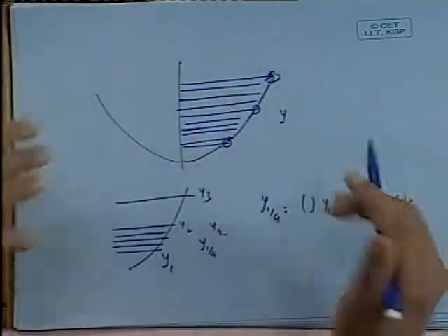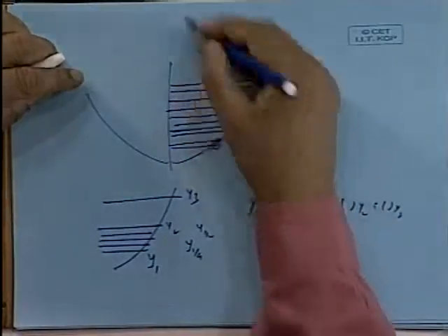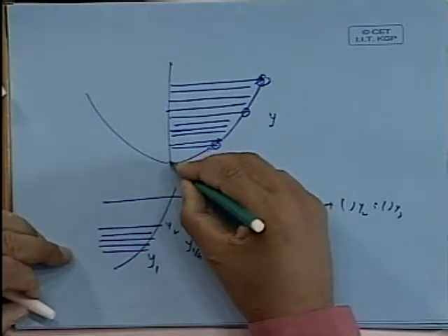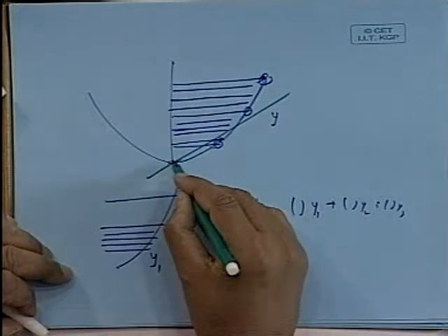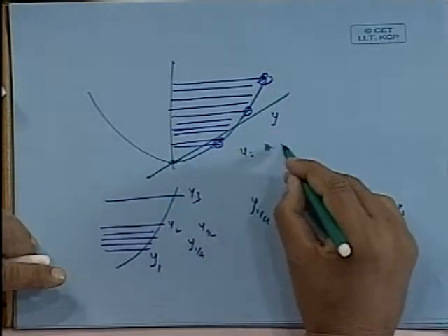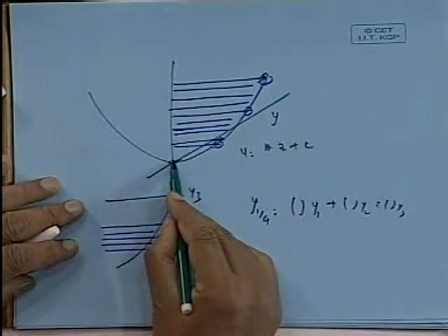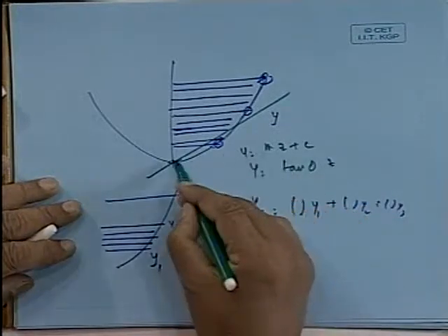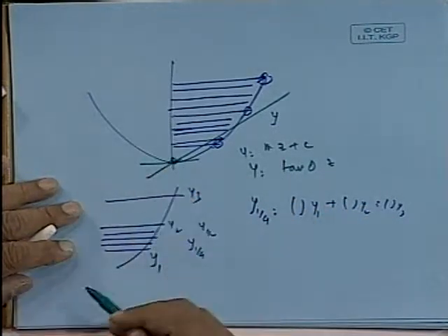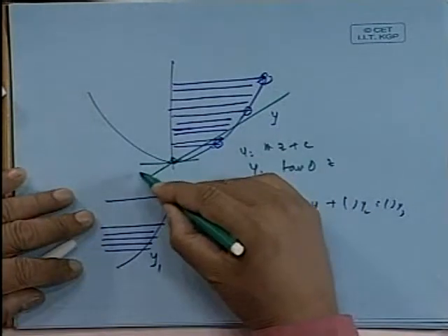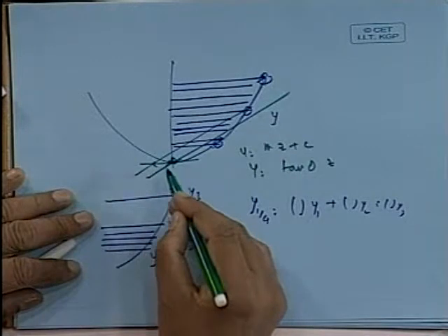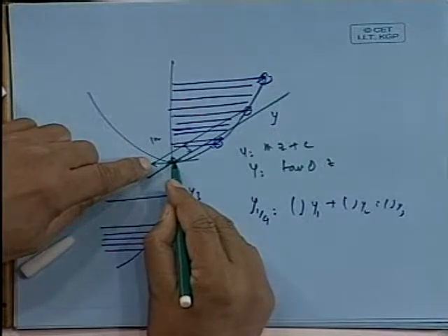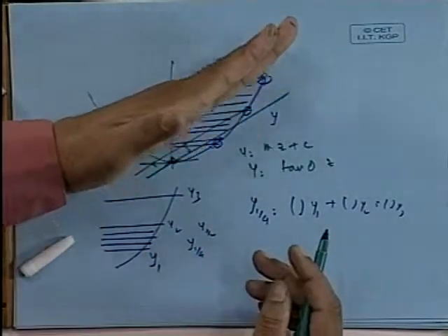You have an offset table, so you start, another question will come, you start this line, you see now there is this line there. So let us say I will start the line from this point, then you will find out that I will fit this y equal to mz plus c. I see that when z equal to 0, y equal to 0, so c becomes 0. So this line becomes y equal to tan theta into z if it goes to this 0, 0 point. Okay. So now I can use the next line where I know that c will be this much. This is nothing but, if the waterline interval is taken to be 1 meter, 1 into tan theta. What I mean is that you can very automatically create these lines.